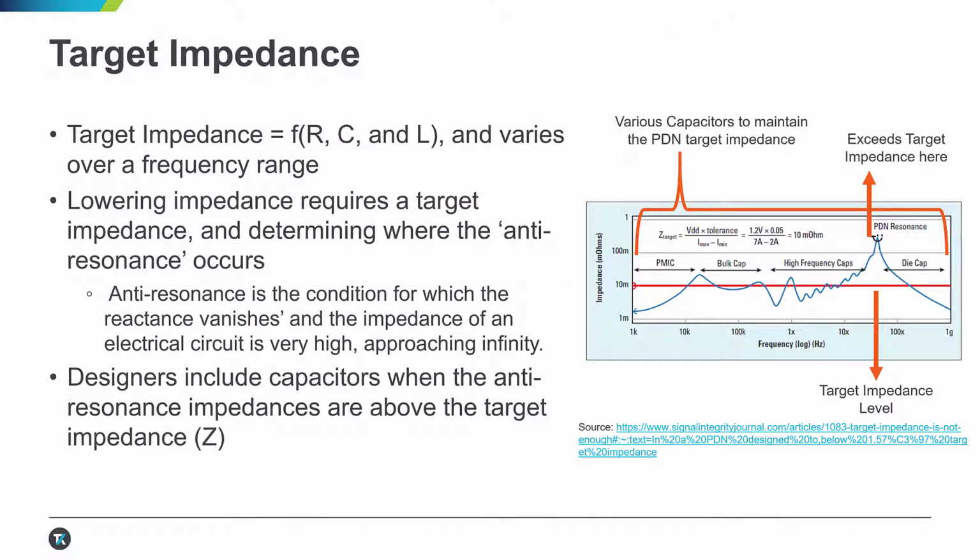All right, we're going to move into our final topic here, which has to do with impedance and how it can vary through the operational frequency of a power supply. So the key consideration for PDN, or power distribution networks, is the target impedance, which represents the upper limit that should be maintained within the system so that the power supply noise doesn't exceed its maximum value.